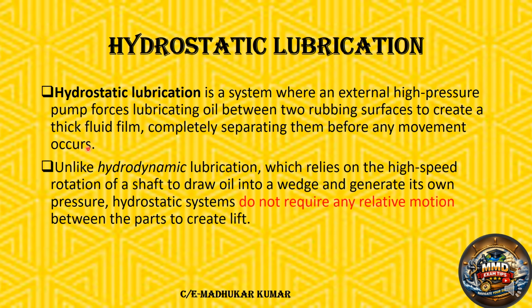So we start the lube oil pumps, especially if we talk about the main engine. The pressure is generated, and the lube oil passes through the rubbing surfaces, bearings, or con rod part. You can see all over where the lube oil is passing through.